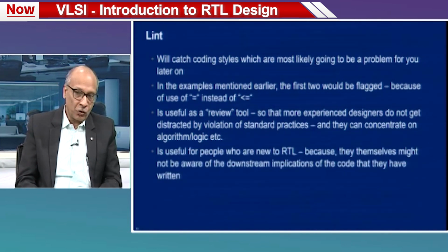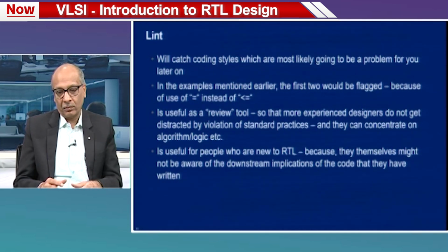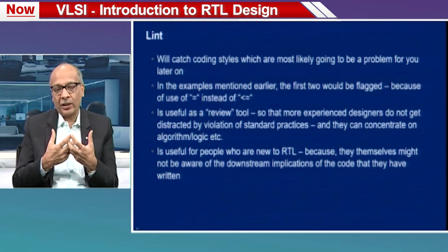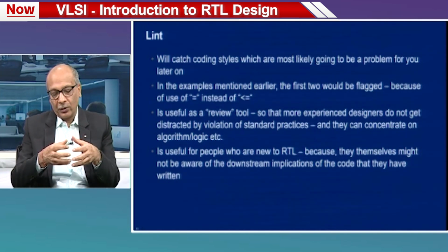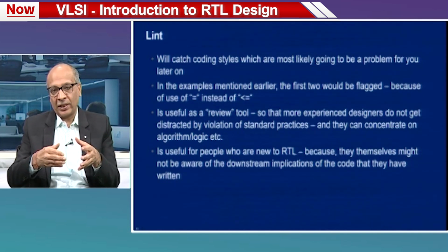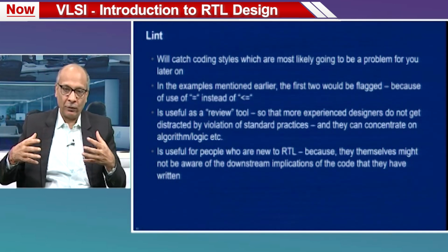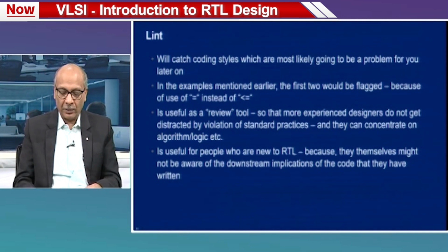Linters are very useful to folks who are new to RTL, since I am new to the RTL world, new to the semiconductor design world, I may not know what could be the potential implication at the later stages of the design flow. So, the linter tool will help with that. Okay.